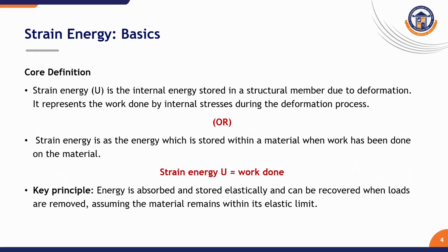Basic definitions of strain energy. Now let us define the strain energy. Strain energy is the internal energy stored in the body due to deformations. In simple terms, when an external load does work on the structure, the work is stored as strain energy. As long as the material remains within the elastic limit, this energy is completely recoverable when the load is removed. Mathematically, strain energy is denoted by the capital letter U, which is equal to the work done by the load. This is the key assumption behind all the energy methods.